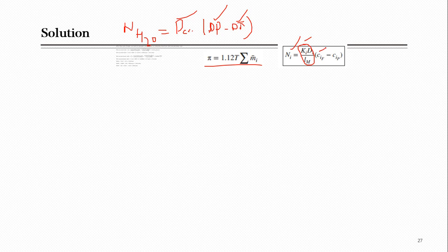So what we will need is the concentration of the feed and permeate side to calculate the salt flux through this membrane. And then finally you have to calculate the concentration polarization. So you can use this formula. The flux of water that we calculated in the first part can be used here. And then there is salt rejection. So salt rejection will be calculated by using Sp is equal to 1 minus Sr.